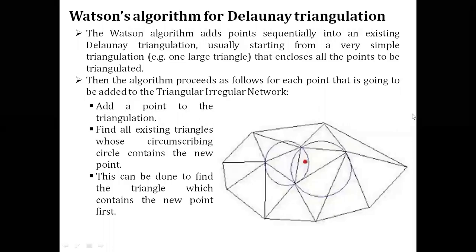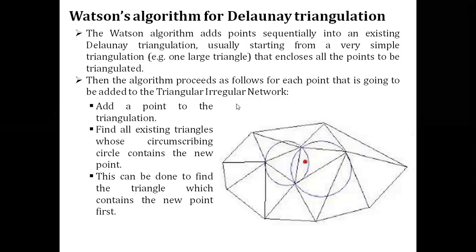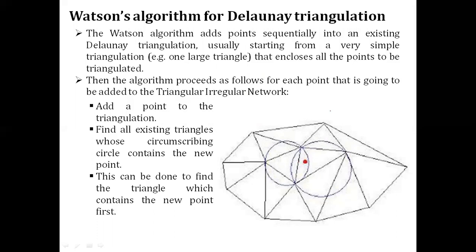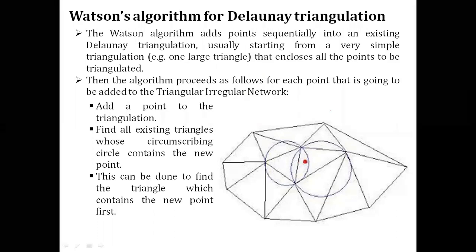So good afternoon, everyone. Yesterday we were discussing the Delaunay triangulation and the Voronoi diagram, which is the basis of all the triangulations that have happened. Today we are going to discuss an algorithm which was developed by Watson and Boyer. This algorithm works for refining the Delaunay triangulation even further with respect to the type of meshes or the type of tessellation that we generate.